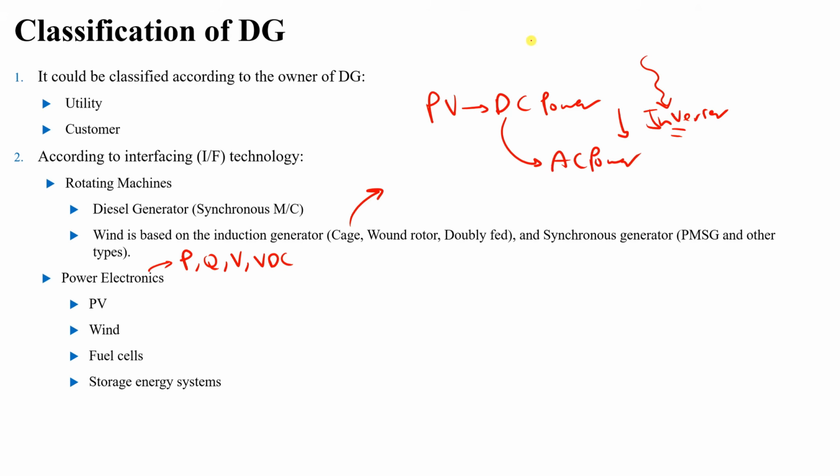What is important now to understand in this lesson is, what exactly is a static synchronous generator? We know that any synchronous generator, as I just explained in the previous slide, lets us control how much active power and how much reactive power. Now we can convert any system into a synchronous generator without any rotating part. Remember, the synchronous machine is a rotating machine. It has a rotor that rotates and the stator, consisting of two parts.